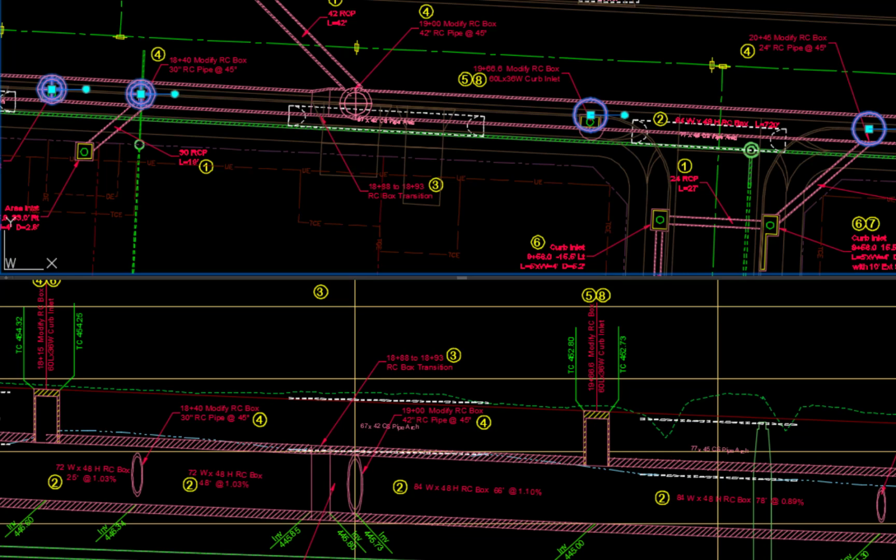Null structures have been located at each curb inlet and pipe connection along the RC box in order to show the invert elevation in profile view. Since modifications are made to the RC box to provide openings, curb inlets and pipe connections can be at different locations. The location of the curb inlets on the RC box have been modified.